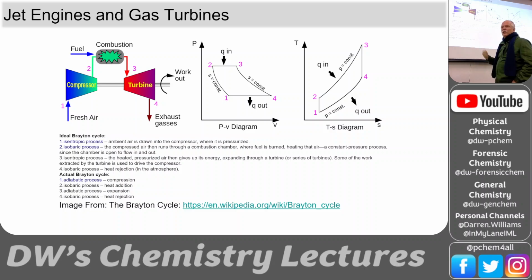So when they spin up a jet engine, it's not generating its own power at first. We're spinning it up with some sort of motor that turns the compressor, and then we light that fuel. And once that fuel starts to turn the turbine, then it compresses its own gas, like it's running itself. But we can adjust this by the pitch of the blades in a jet engine. So the compressor blades are pitched a certain way to compress the gas, and then the turbine blades are at a certain pitch to capture as much energy as possible.